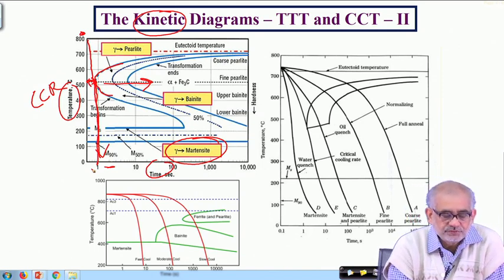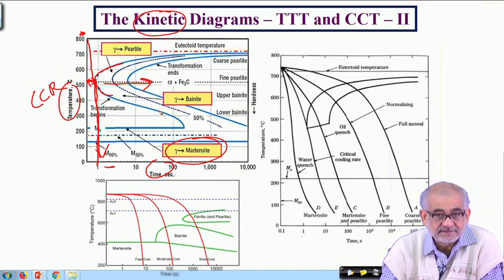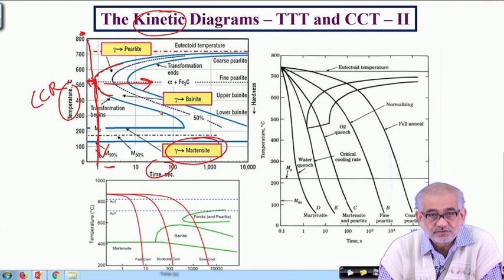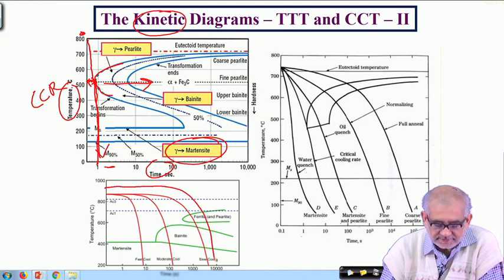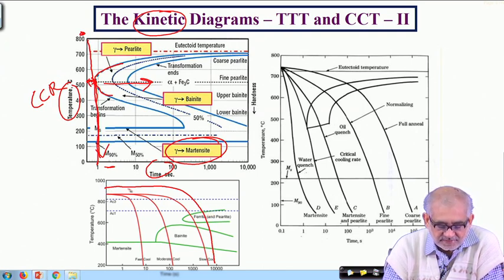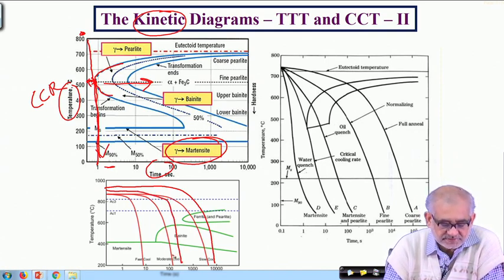So in order to make life easier, to be able to not only avoid the intersection with these pearlitic or bainitic parts, also if we want similar slow cooling somewhat like this, where I can take life easy and cool slowly like this and get pearlite. If I cool slightly faster, then I actually can get into bainite and make a full bainitic microstructure.